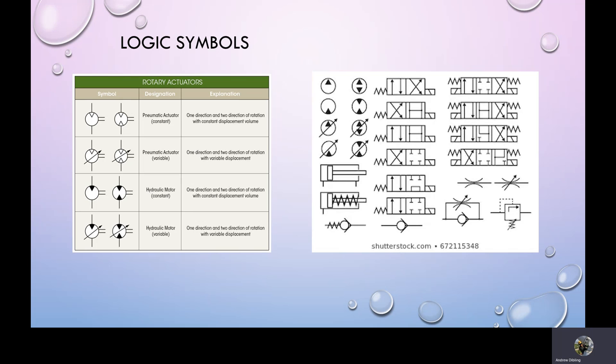For instance, if you're using a closed center, an open center where all 4 of the valves are connected together, so the pressure is equalized no matter where it is in the system, and the second one down on the right-hand side, you have the regenerative center position, which we simulated in the lab by using the manifolds, if you remember. I pointed that out. And of course, below we have restrictions, flow controls. We have variable flow control, static flow control, and then we have a flow control that's variable with a check valve. And again, the very bottom last one there, the schematic symbol, is that of a pressure reducing valve.